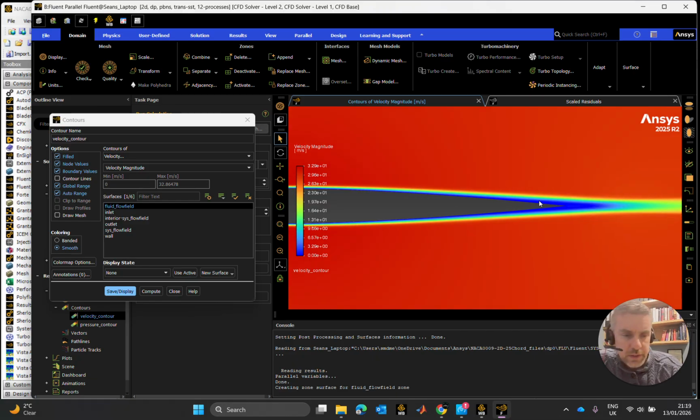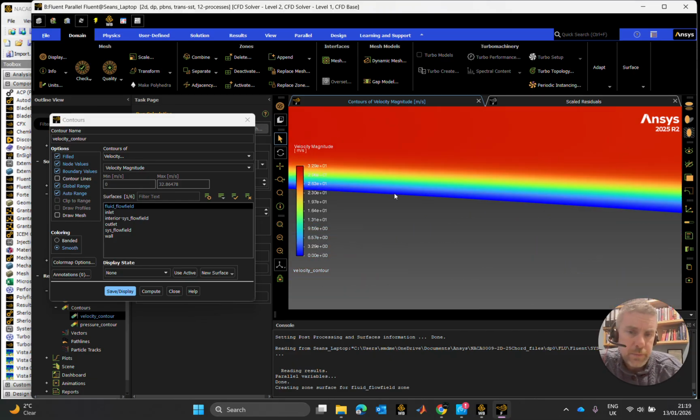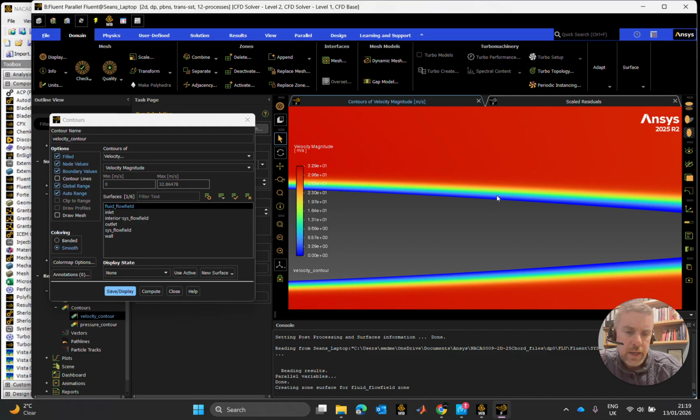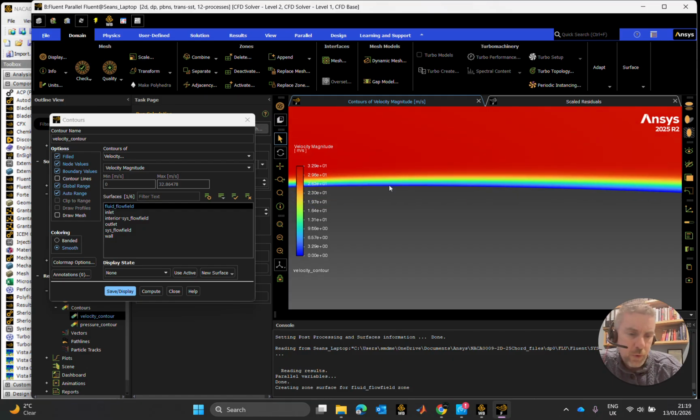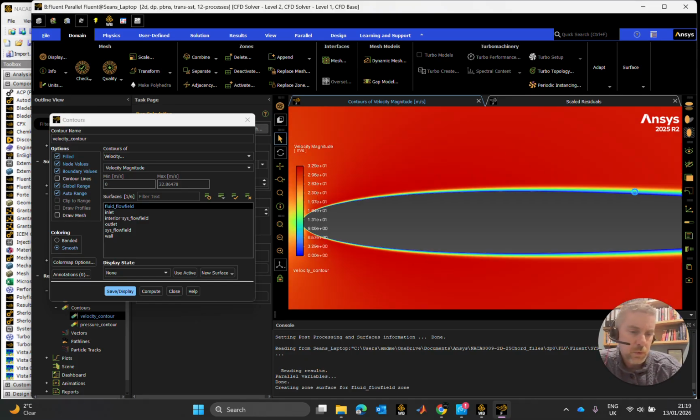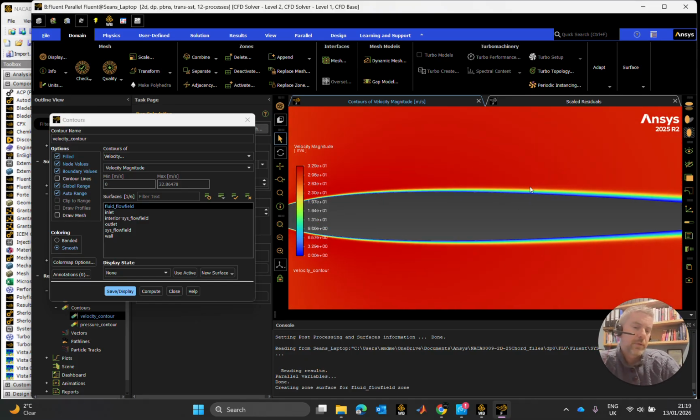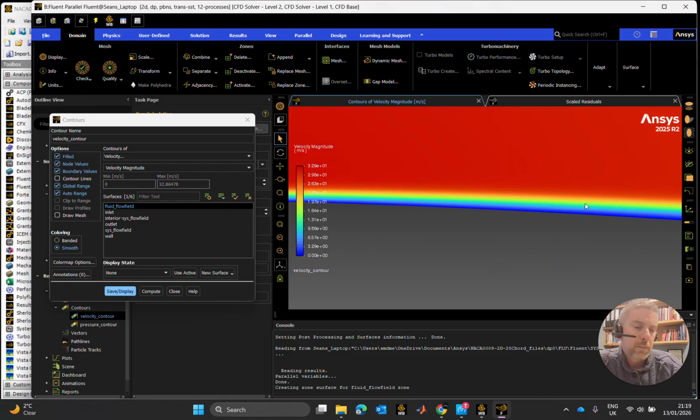which I will say is, I think, odd. If you looked at an NACA 0012 airfoil, especially at 50,000 Reynolds numbers, there are papers written on the laminar separation bubbles, where you'll start to see the flow separating from the airfoil at various normalized chord lengths, before reattaching again. When they pick up a wee bit of energy from the free stream, they come back down, and in some worst case scenarios, they don't reattach at all, and the separation bubble bursts and causes a stall, which is a massive drag effect. But anyway, them bubbles appear on here.